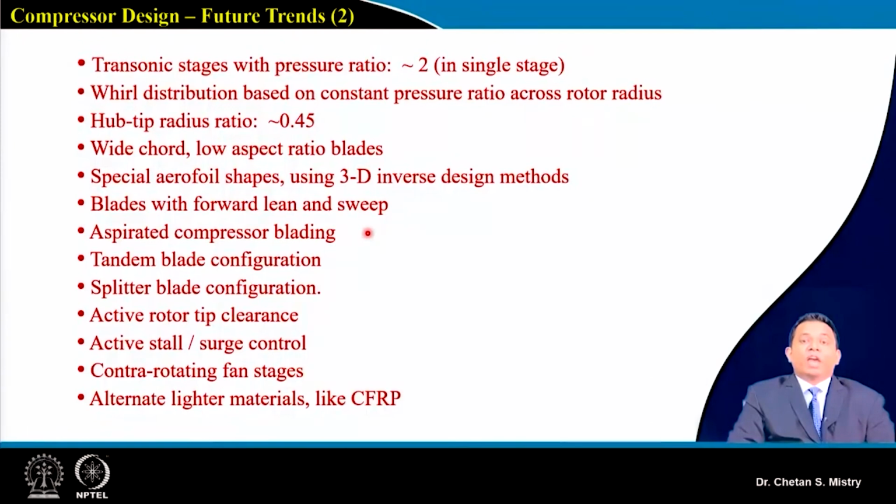Now later on for LP compressor also, people are looking for this kind of configuration, with per stage pressure rise to be higher, and we know what all the reasons are, what all our expectations from the designer are at this moment. Then we are looking for the work distribution based on constant pressure ratio across the radius. So this is what is important, what we have realized up till now, what all design methodology we are